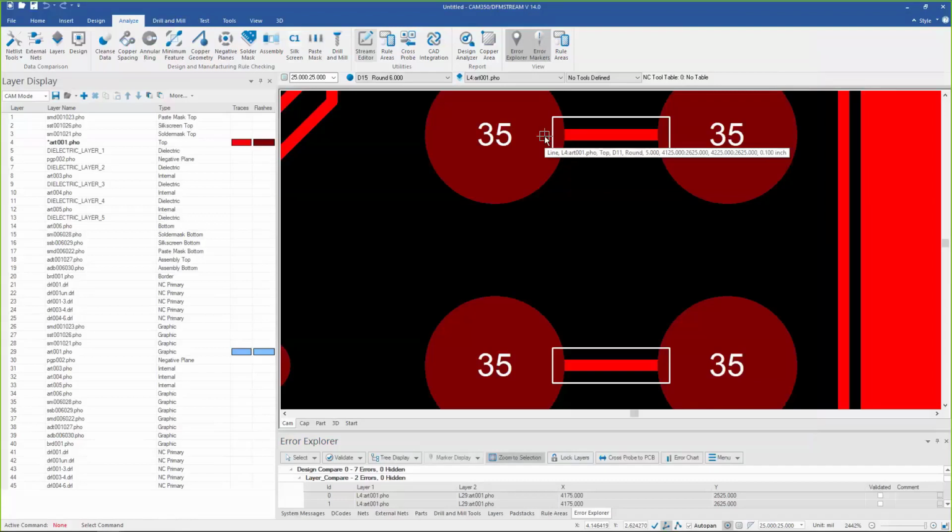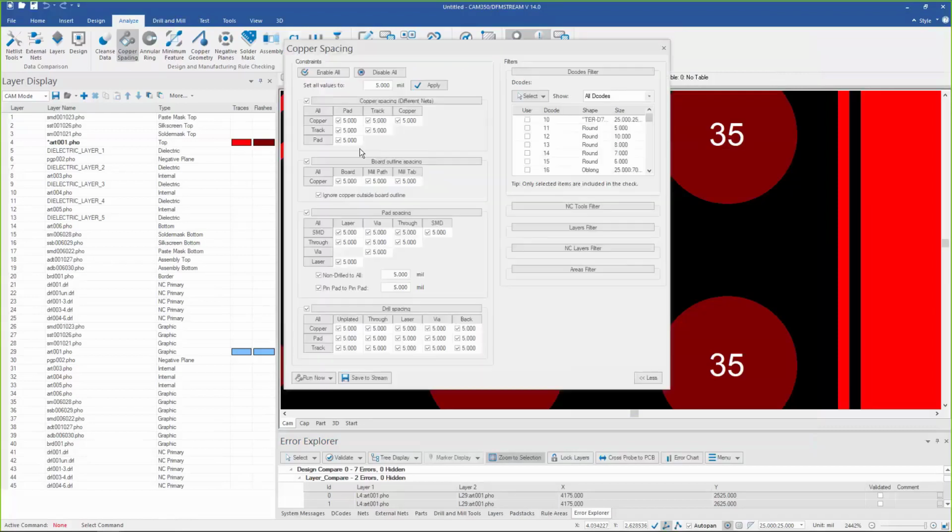One of those is if you have dummy nets or dollar mark none nets, or no connect nets, you can now filter those out from the analysis, which you could not do in the old manual way. The other thing we've done is you now can just run a particular type of analysis without having to add it to the streams checklist.